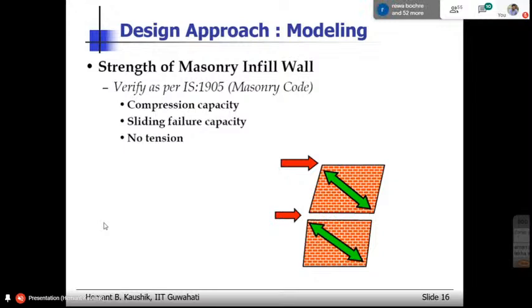We can say that this is masonry and this is the compressive strength of masonry prism. Like we say that this is a concrete column, but this is the characteristic strength of the concrete cube. We cannot say that this is the strength of the column, because when we talk about material, it is the concrete cube. Similarly, in masonry, we can say that this is the compressive strength of masonry prisms.